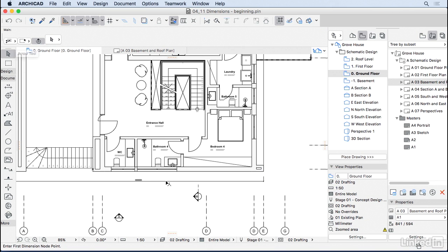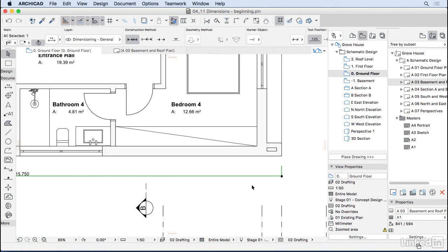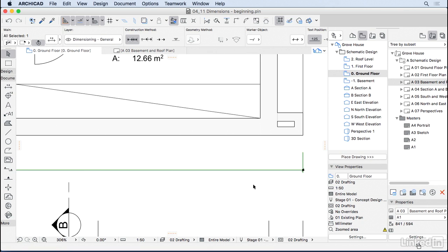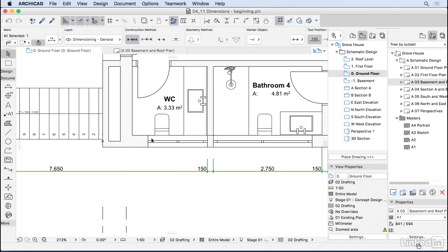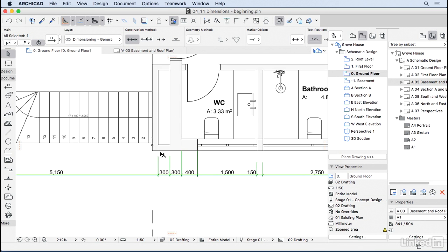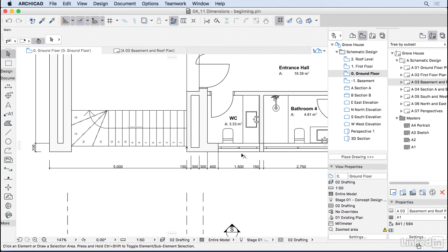Now with the arrow tool, I'm going to select this dimension, and then holding Command on the Mac or Control in the Windows, you can go back and start adding new points to this dimension line. So now we're breaking that dimension line in the points that I want. The reason why I prefer this method is because when you are adding the points for the other dimensioning, I'm adding the points here, and then I get one point wrong, and sometimes I hit escape and I lose all the points. So I prefer to do the first and the last one because I think it's faster.